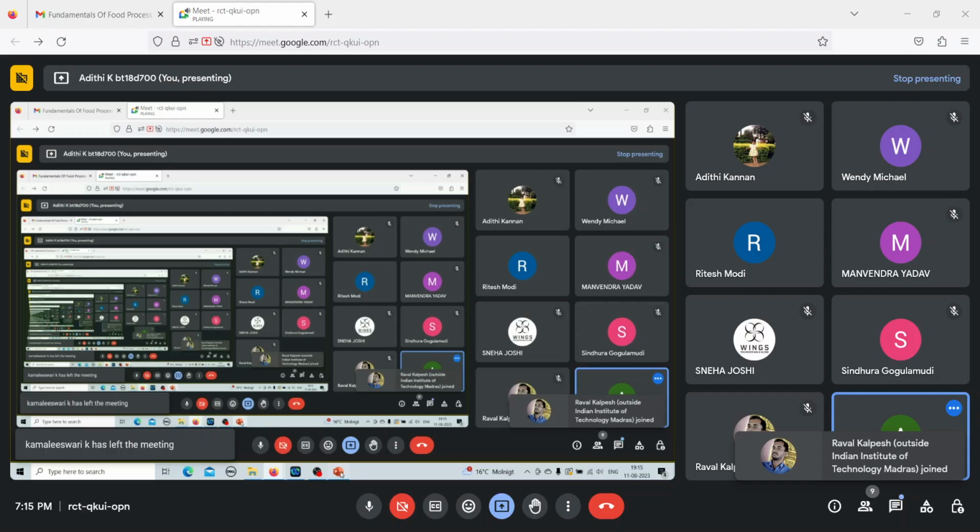I do not know what the decimal reduction time is. I have no clue about any of the parameters. I have only the temperature and the number of changes in the microorganisms. But we need either K or D to proceed to calculate the time. So I'm trying to calculate the decimal reduction time at 130 degrees Celsius. From there, I'll calculate the processing time required. So we'll proceed with this.